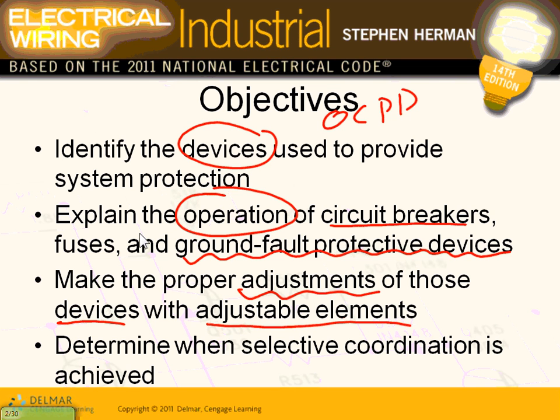You have a 2,000 amp circuit breaker. You can adjust this 2,000 amp circuit breaker to 200 amps. When you adjust the trip to 200, the 2,000 amp circuit breaker is now treated as a 200 amp circuit breaker. Who cares? Well, when you size your conductor, yes, you're tying it to a 2,000 amp circuit breaker, but no, you're not sizing the conductor for 2,000 amps. You're sizing it for 200 amps. That's kind of weird. So we size based on the trip. Big, big deal. Selective coordination.